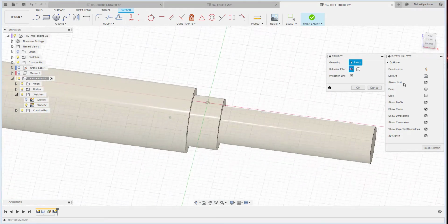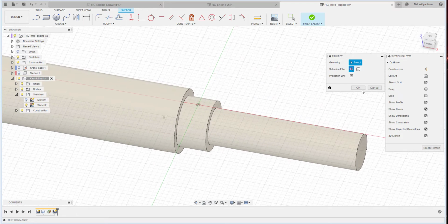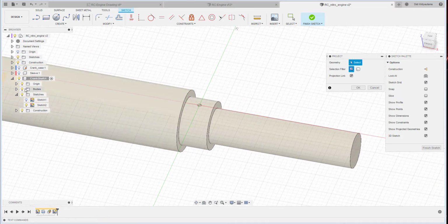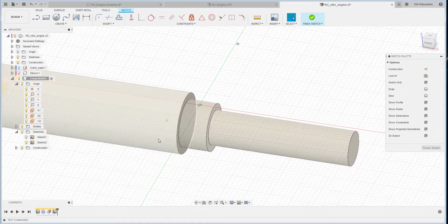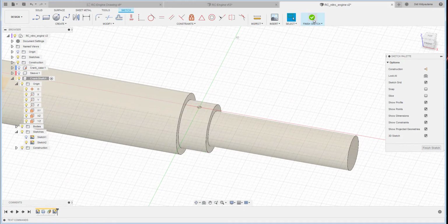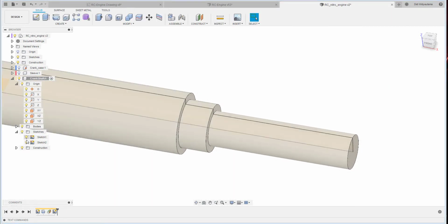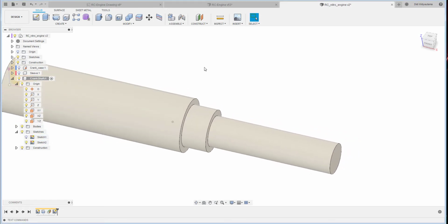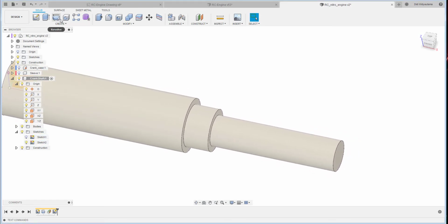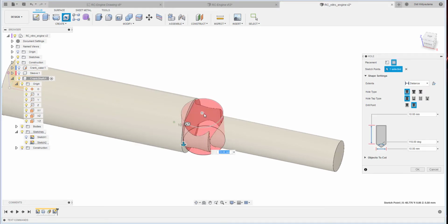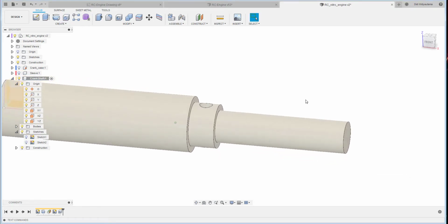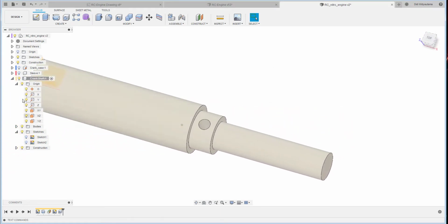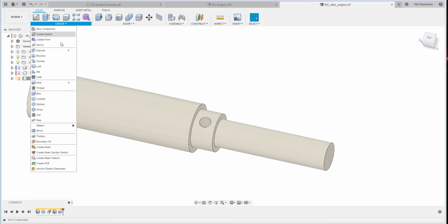Okay, and then I project the center point. So maybe I will open that one. Okay, project, so there's a center point, and then I will create a hole over here. So this is the face, and then should be through hole 3.125, the diameter. Okay, there's the hole, and then I continue with the create thread here.